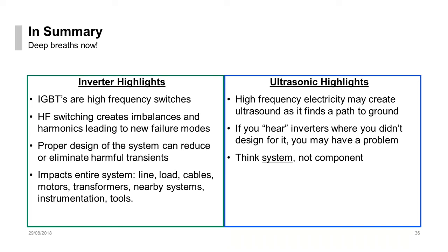And again, think system, not component. If you have a motor failure, but you're on a VFD, you really need to think about the VFD. Could that be a cause for your failure? If you're looking at something even on the line side of your inverters, could there be a connection there? I highly, highly recommend that in those sorts of cases, you look at your power quality very closely.